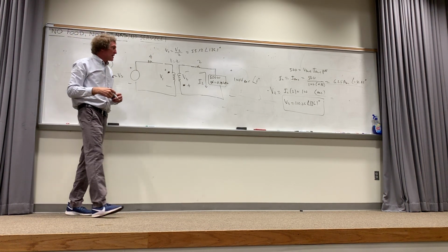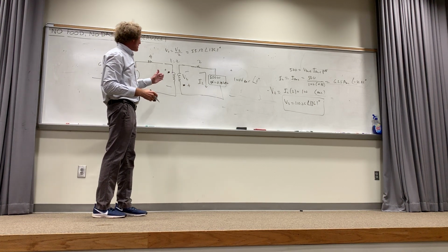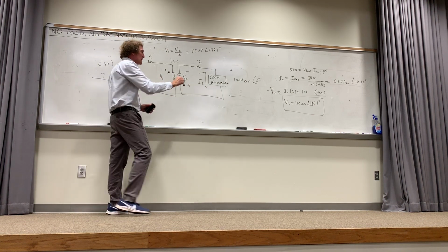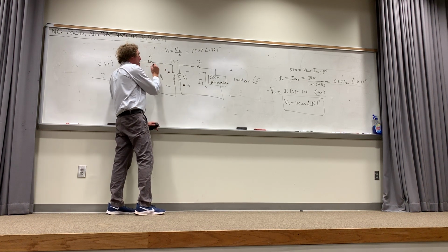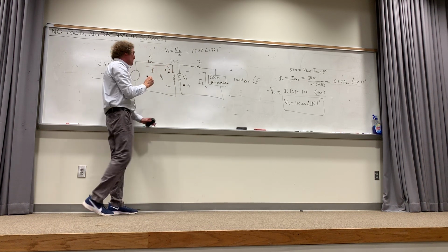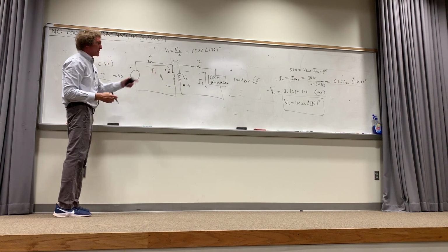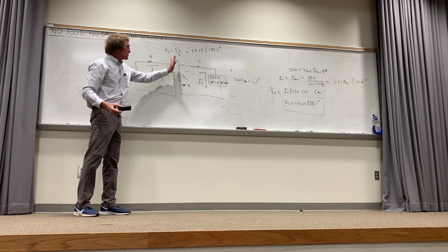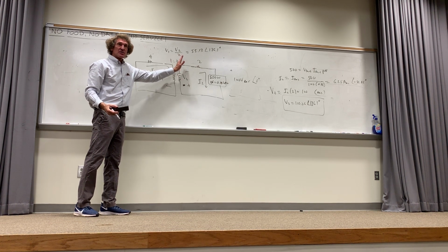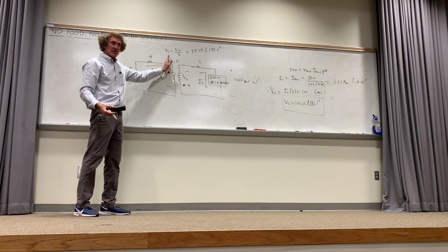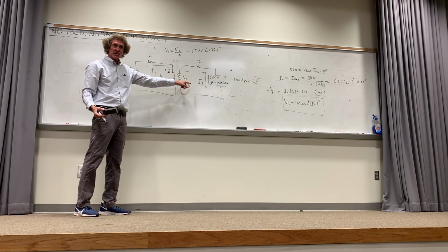Now, if we have that, if I want the primary current, you'll notice I2 is going into the dot, right? Therefore, the value of I1 will be given by just what? Well, it's 2 to 1, right? Twice as much voltage here, 1/2 as much current as the current here, correct, class? So now the current is going to be 2 times I2. Do you all see this?